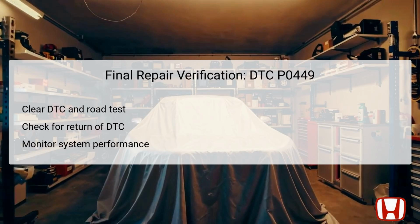After performing the necessary repairs for DTC P0449, it's crucial to verify the effectiveness of the repair work. Start by using the Honda Diagnostic System, HDS, to clear the DTC from memory, which resets the computer and prepares the system for fresh diagnostics. Following this, conduct a road test under various driving conditions to allow the EVAP system to operate fully, ensuring all components function correctly. During and after the test, check if the DTC reappears.